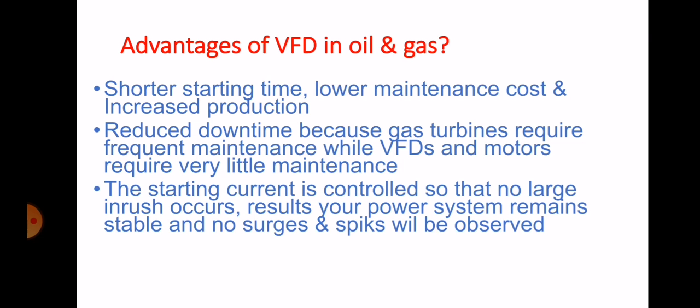And the next advantage of VFD is reduced downtime, because gas turbines require frequent maintenance, while VFDs are motors and require very little maintenance. And the next advantage is the starting current is controlled so that no large inrush current occurs. As a result, your power system remains stable and no surges and spikes will be observed. There is no disturbance in your industrial power system. These are the major advantages of VFD in any oil and gas industry.